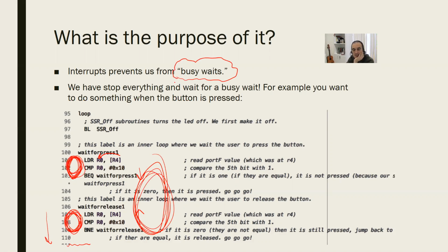Busy wait is a very common element in embedded programming. I mean, you will need busy waits. But while busy waiting, you are not able to do anything else. So you are stuck. You are frozen. While doing busy wait, your microprocessor is useless. So we are dreaming about a mechanism which will be able to get a trigger like this, a switch, however, won't stop doing its job. It will be able to run code while waiting for an outside trigger. Okay? So any questions about busy wait here before I continue?